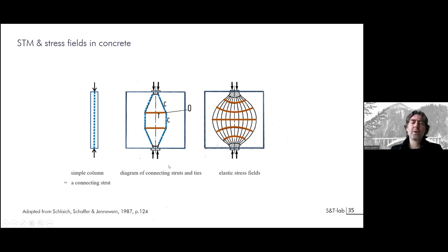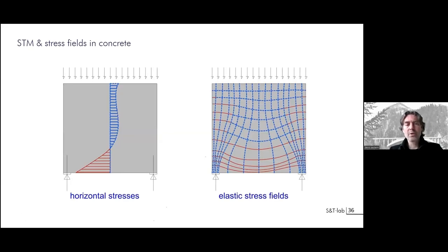This will be the resulting strut-and-tie model, showing that you have compression in one direction with a bulge, and tension in the perpendicular direction. That's typical for assessing concrete shear walls. So the approach followed by the School of Stuttgart is first seeing that you have a nonlinear system, so you cannot apply the theory of elastic behavior. And for this, you draw the elastic stress field.